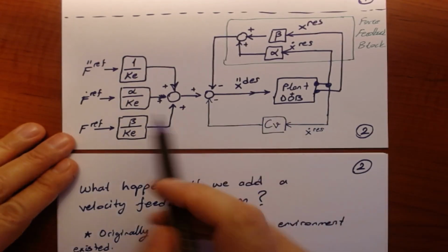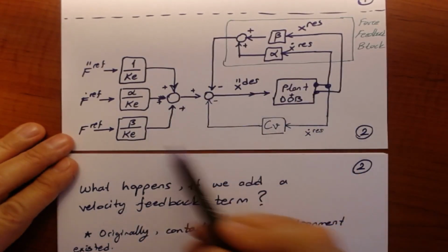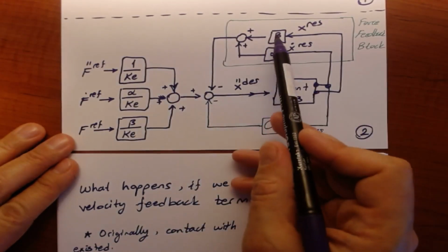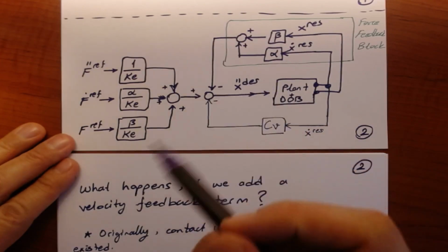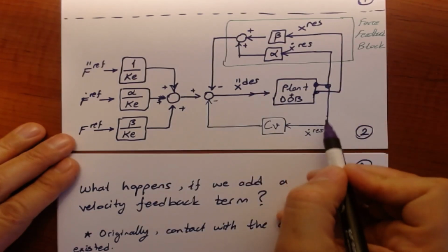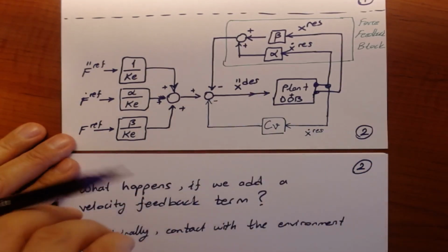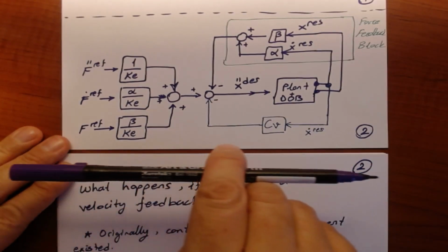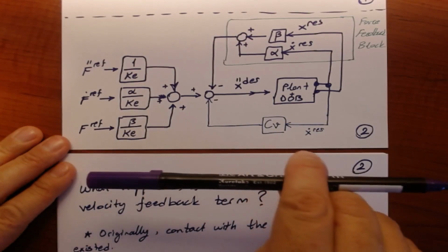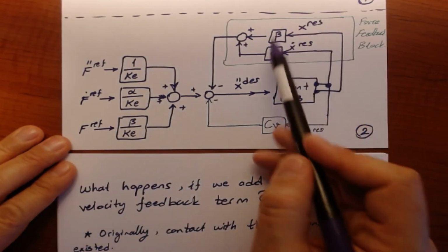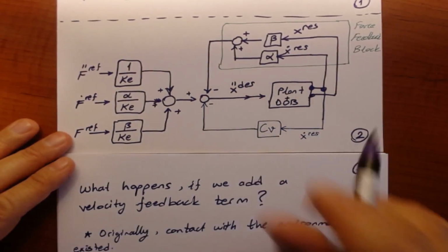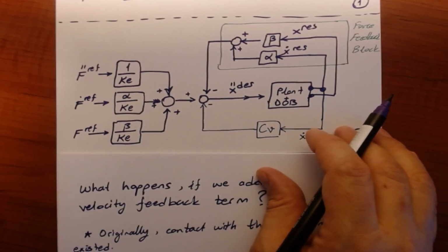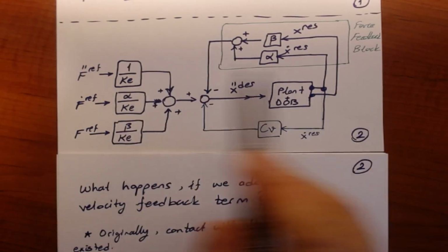When you add that, you simply change the dynamics of the closed loop control, and even though there is no response from the environment, there is no environment deflection, with this velocity feedback what you do is simply gently approach the environment and then touch, and after touching you have the response position and velocity from the environment. It's the deflection of the environment, and that gives you the opportunity to start force feedback, and all of this happens naturally in this block diagram.